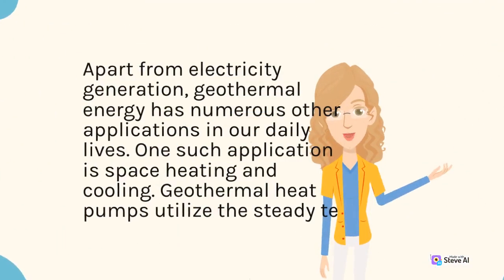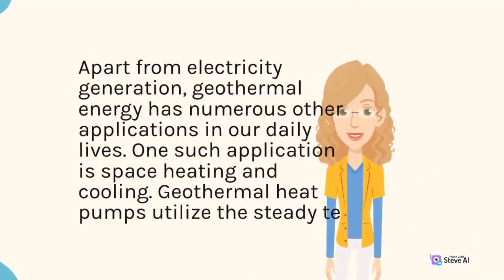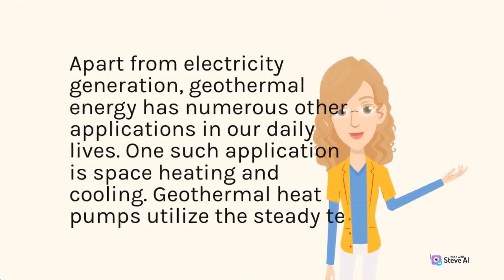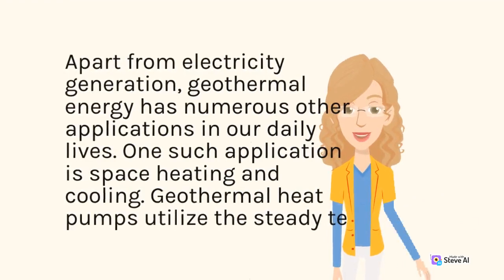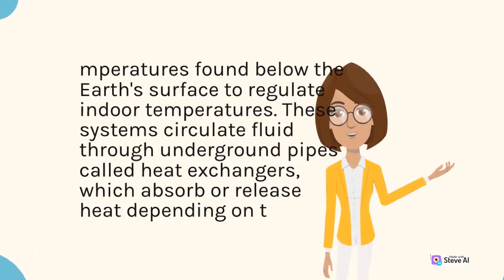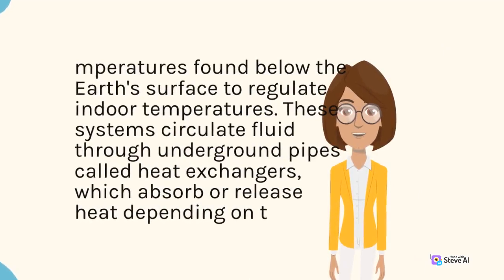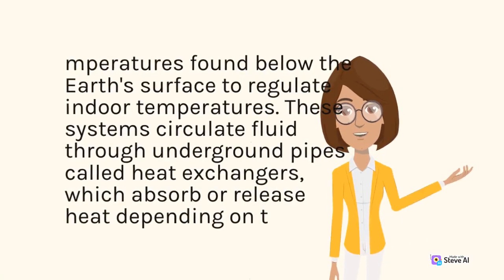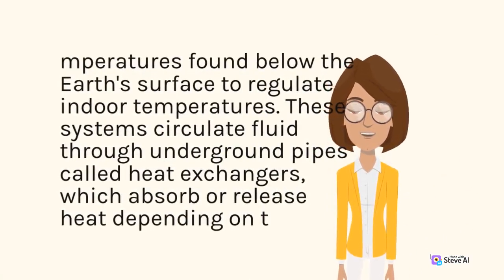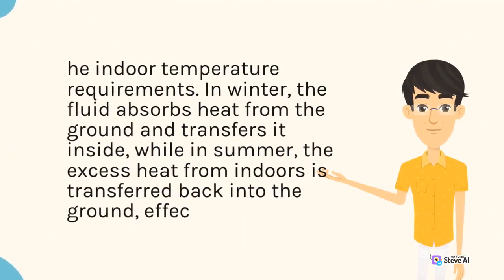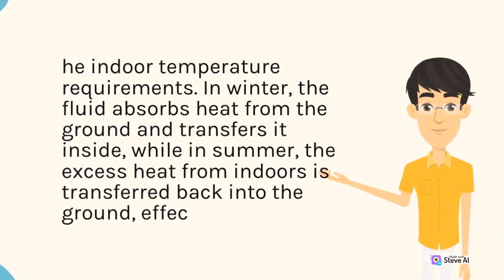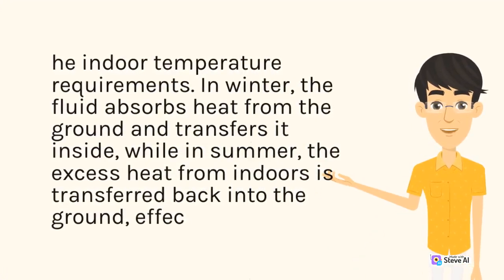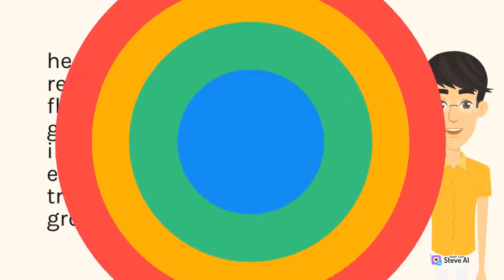Apart from electricity generation, geothermal energy has numerous other applications in our daily lives. One such application is space heating and cooling. Geothermal heat pumps utilize the steady temperatures found below the Earth's surface to regulate indoor temperatures. These systems circulate fluid through underground pipes called heat exchangers, which absorb or release heat depending on indoor temperature requirements. In winter, the fluid absorbs heat from the ground and transfers it inside, while in summer, the excess heat from indoors is transferred back into the ground, effectively cooling the buildings.